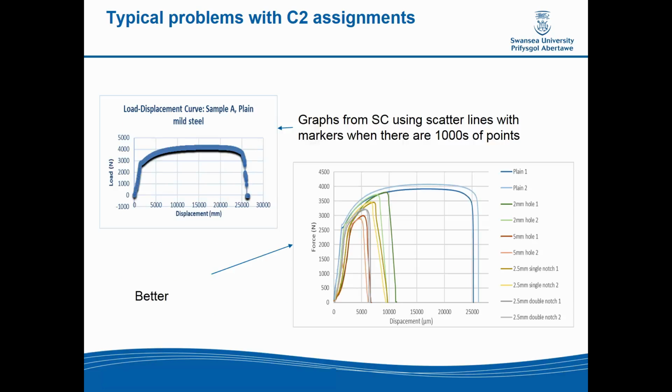Right, graphs. Just to give you an overview of what I would consider to be not so good and a bit better. When you're doing load displacement curves, there are a lot of points, possibly thousands of points. Don't put big markers on them because you'll just cover up all the curves. That one on the left up there has a lot of markers on it. You can't even see the curves below it. Immediately it starts to look cluttered and you can't make head or tail of what the data's doing. So it's better to say, right, no markers on that, straight lines.